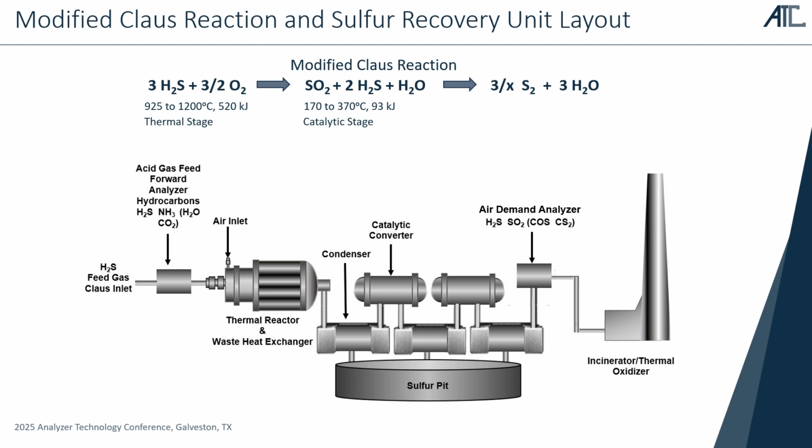As soon as you move off that ratio, things like your emissions are going to go up. If you have a tail gas treater unit on the back end of your plant, you can do damage to the amine, or if it's a SuperClaus plant, you can have thermal excursions. All sorts of bad things can occur by having a dramatic swing off ratio.